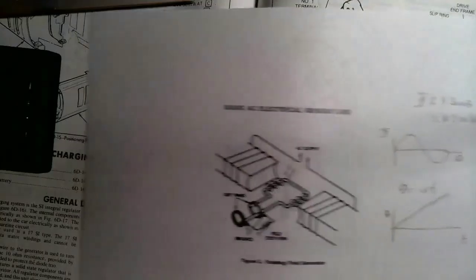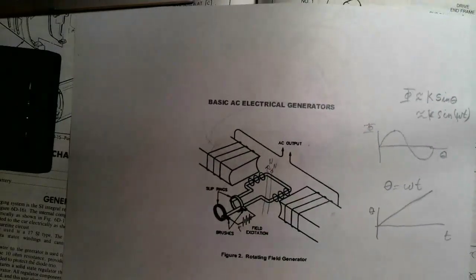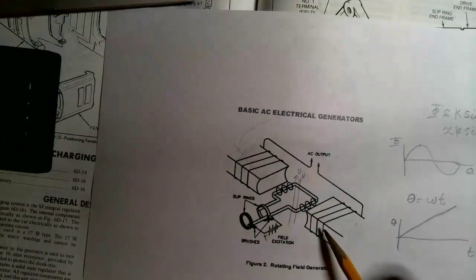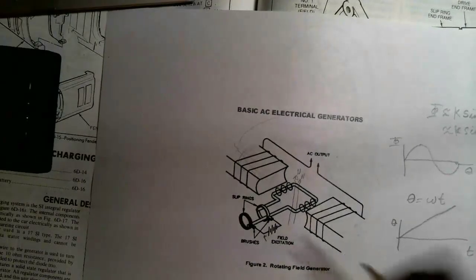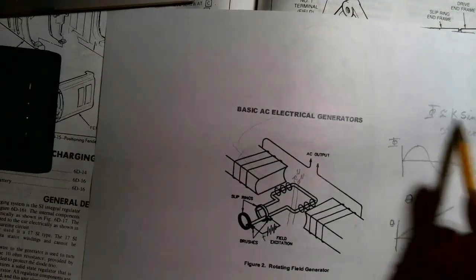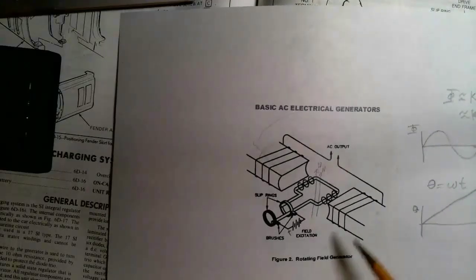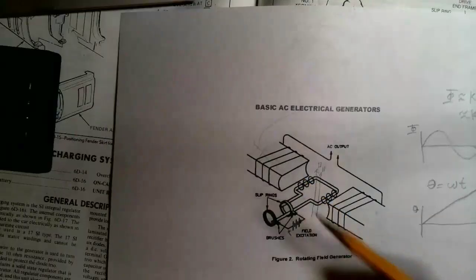Now, Faraday's law says that to get a voltage around the loop, we don't need a magnetic flux, we need a change of magnetic flux. So the voltage around any loop is proportional to the rate of change of the magnetic flux. And so if our magnetic flux looks like this, then our voltage around any given loop, and this would be one loop, like one turn on this coil right here, would be one loop.